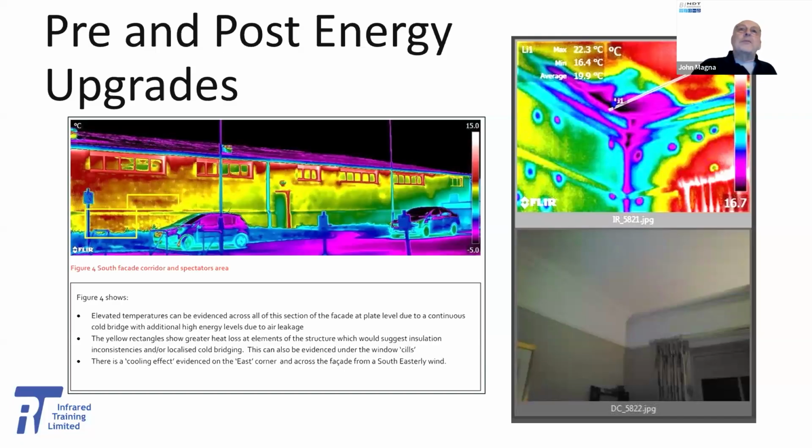The house had achieved the required passive house air change figure of better than 0.6 air changes per hour at 50 pascals pressure differential, demonstrating that the anomaly wasn't as a result of through air leakage. Difficult to find without the use of infrared, and this type of heat loss will increase with wind speed and temperature difference. Thermographic building surveys can often help to inform developers where weaknesses in the thermal envelope exist and demonstrate that they've been addressed post any remedial works.